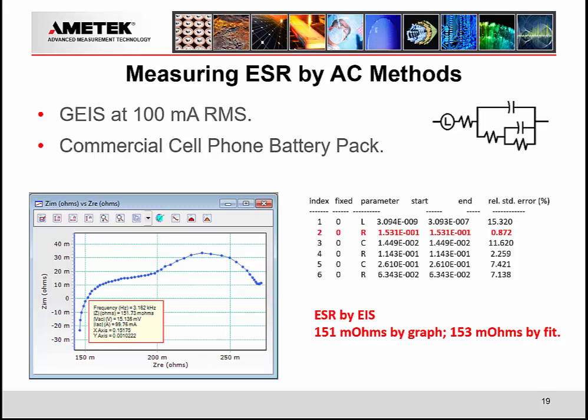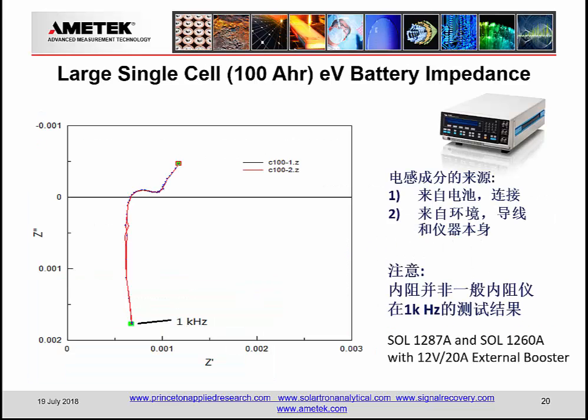And so a pretty reasonable close approximation of my ESR, really just graphically, without any added complication of using equivalent circuit modeling. So all this higher technical content is available for you through the circuit modeling strategy, but I want you to understand that you can benefit a lot from impedance analysis if you're looking for key figures without going to that level of detailed analysis.